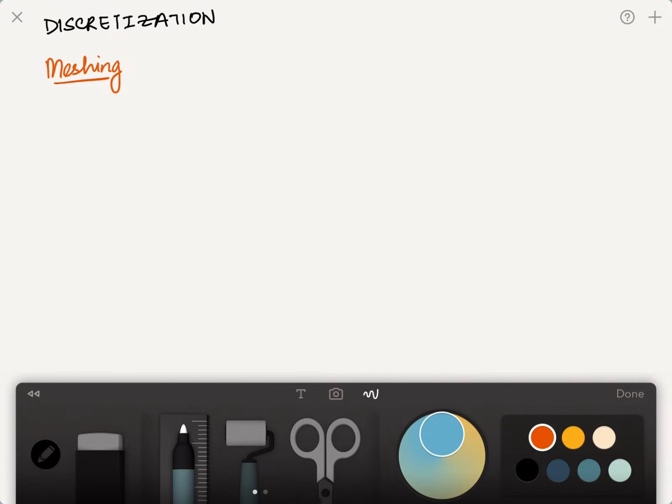And depending on the kind of structure it is, the parts can be of a certain dimension, and those are actually elements. So the entire process of, first of all, dividing a structure into smaller parts and then deciding where exactly these smaller parts are, where do they join each other, where do you want the nodes to exist, comes under meshing or discretization.